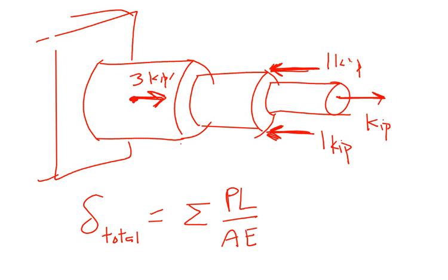No, right? You would get 2 totally different internal forces. So this very first piece you can't treat as one segment. You have to treat it as two segments.